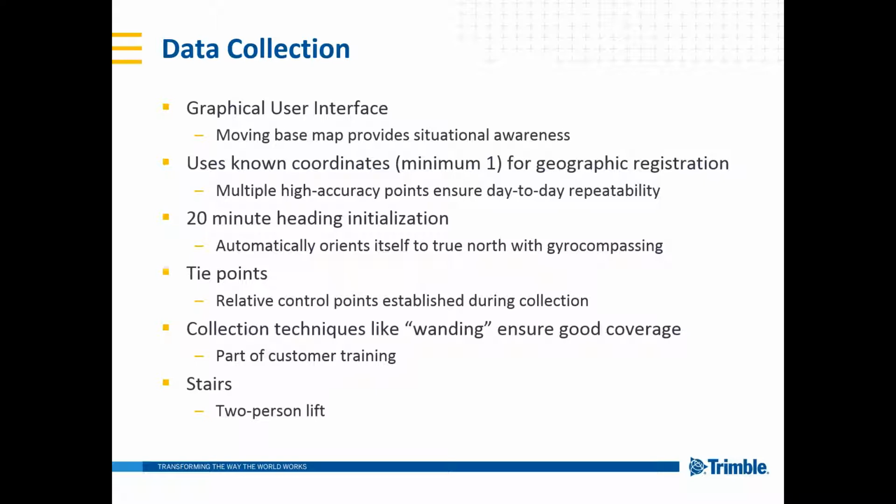We are going to talk about a 20-minute heading initialization. So our systems, because they're georeferenced, they need to know where north is, but because we use a very good IMU, it is able to resolve north on its own. It's sensitive enough to sense the Earth's orientation and the Earth's rotation and orient itself accordingly. But that takes about 20 minutes. We're going to do that once a day. We're not going to redo it when we change floors. We're not going to redo it after a certain period of time. Once we do it once, it's good for the rest of the mission.